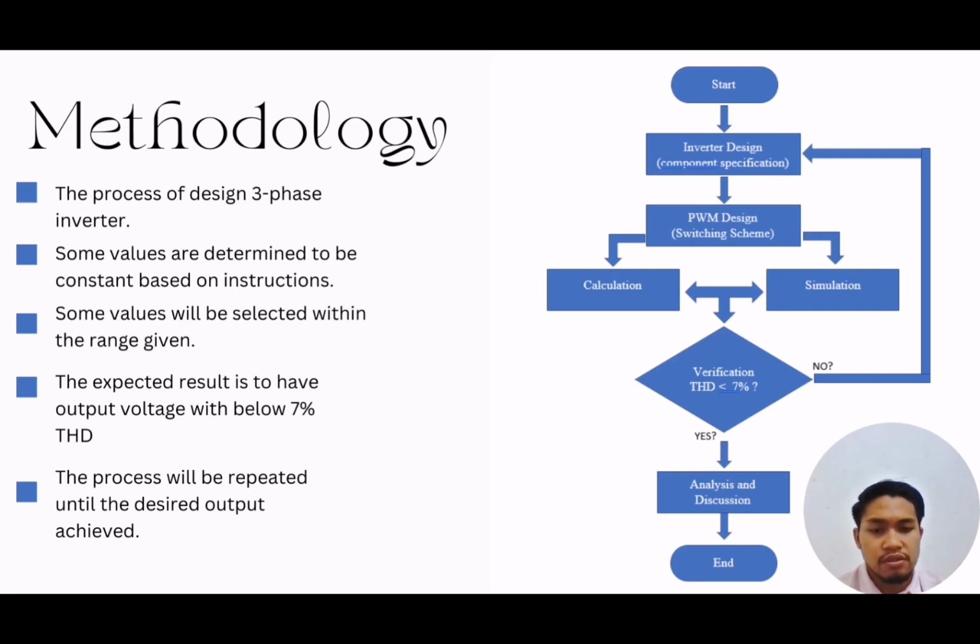If the verification is no, which is the THD is bigger than 7%, we will go back to the inverter design and do some adjustment of the values for the components, and the process will be repeated until the desired output is achieved.